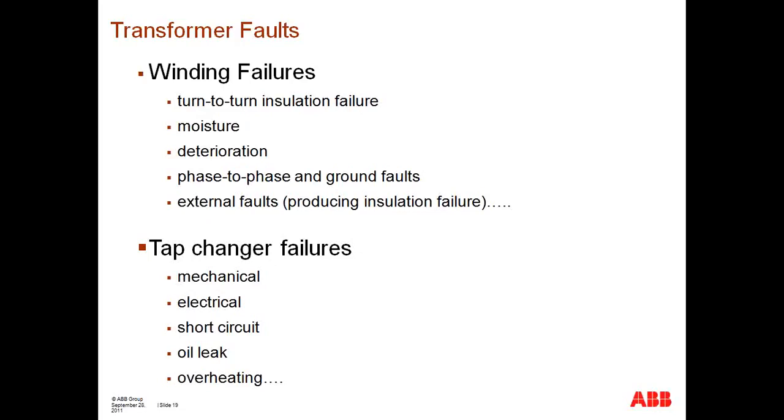Think of some of these failures as the result of the following. Some of the insulation in these transformers could be in the form of some sort of varnish or some sort of resin. And as you could picture, these varnish or resin type components are relatively brittle, or they become brittle over time. So when through faults occur, or when the transformer is stressed, there's not only electrical effects, but also physical movement because of the magnetic forces involved with high levels of current.